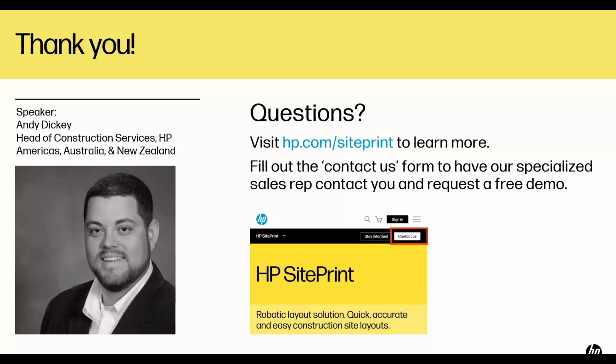I think you mentioned this before, but how clean must the site be before printing? Yeah, it can be pretty dirty. I don't know how to quantify it. That's something we all kid about on this team, is that we tell people chalk clean. Whatever you're going to do for your normal layout in terms of cleanliness, do that. But there are some applications where a little bit of dust on the slab is actually a good thing, because when the dust blows away, there's ink left and it's a very crisp line. I encourage you to buy one and test it. It's hard to quantify, but it can be pretty dirty.